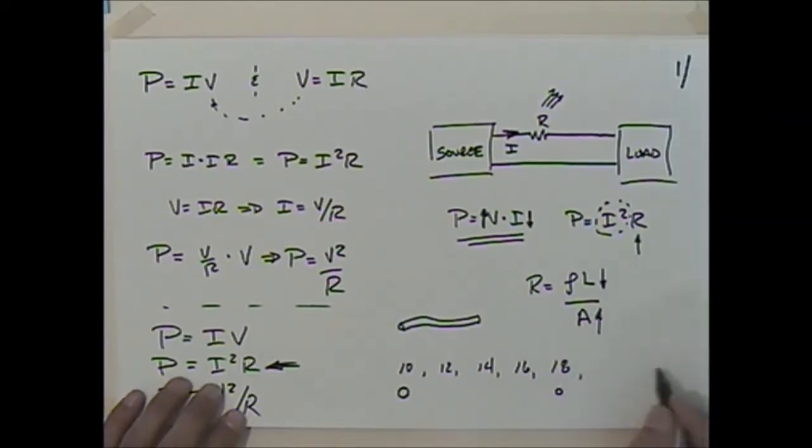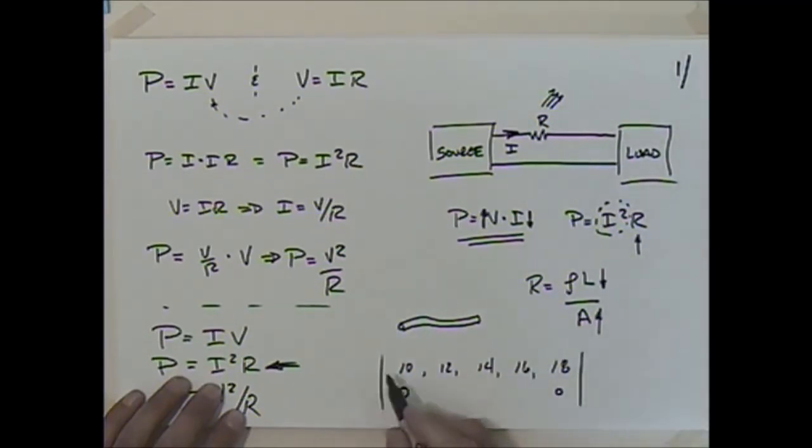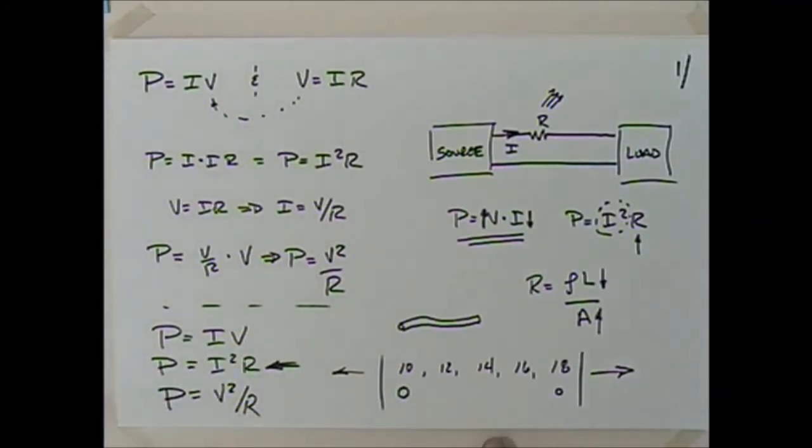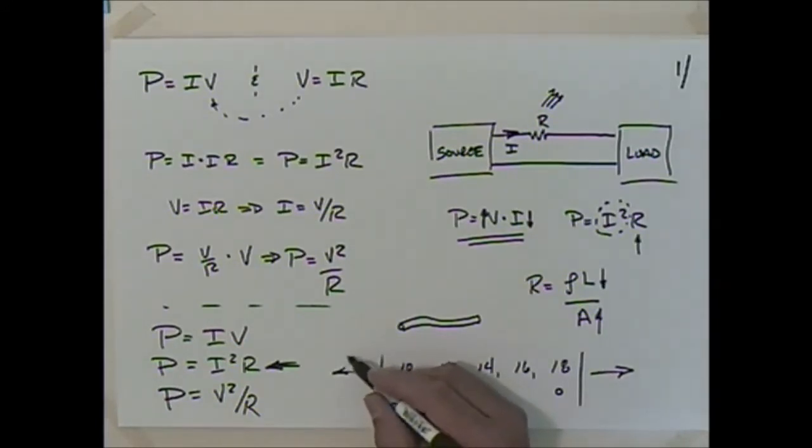And these numbers continue on up and they continue down. Usually you're not going to get extension cords out of this range, but as far as wire sizes, this continues this way and that way. And it's a little bit unintuitive in that the smaller the number, the larger the wire size. And when it gets down to 0, then it starts having 2 zeros, or double aught, triple aught, and so forth.